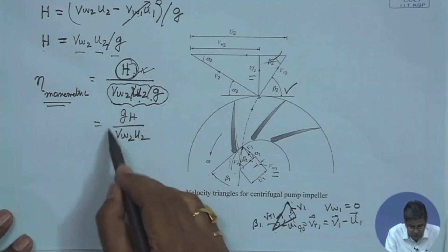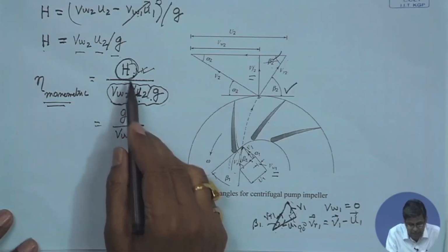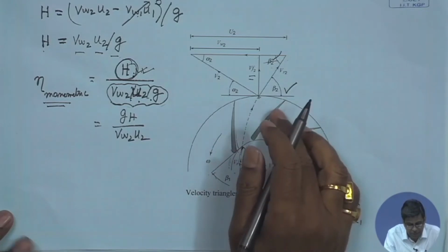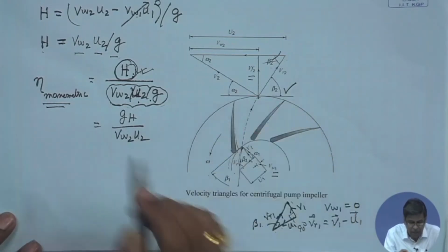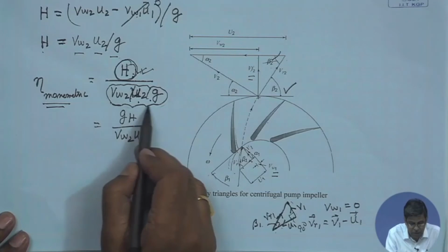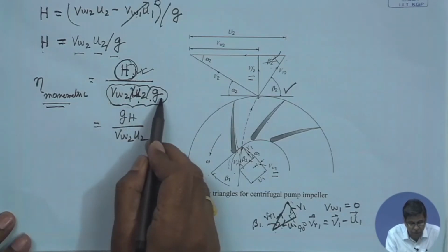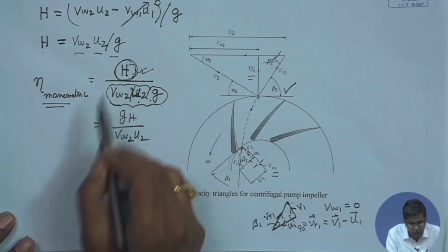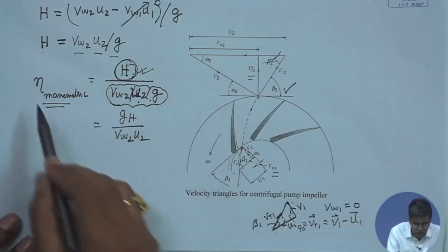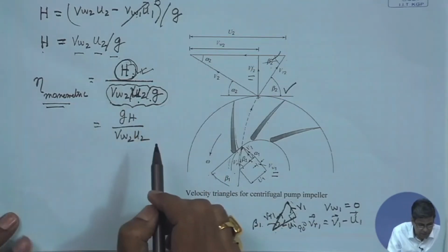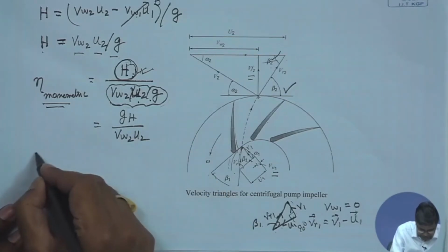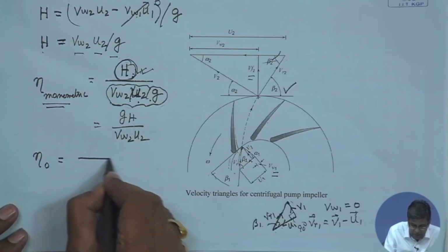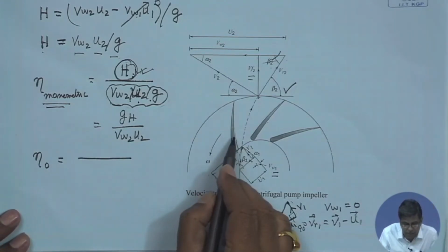So, this manometric efficiency takes into consideration the viscous losses, that is the fluid friction. This is the discrepancy between the head given to the fluid by the rotor and the head developed by the fluid while flowing through the pump. This is defined as manometric efficiency. Then another efficiency, as you know, eta overall, is defined as how the overall efficiency is defined.